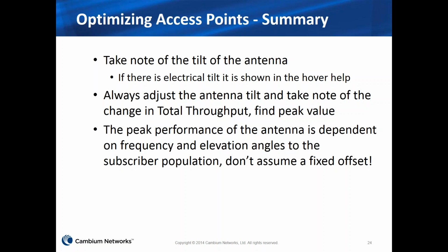Where we're also seeing a need to go through this process is if you have sectors which are already planned or deployed with PMP 450 with original antennas, and you want to look at the improvement in performance you may get by switching to PMP 450M with its antenna with the down tilt. Then you need to do more than just change the product from PMP 450 to PMP 450M. You need to also adjust the tilt, otherwise you won't be seeing the best that the 450M can give you.